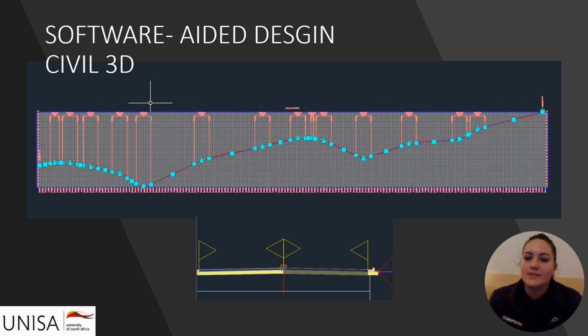The corridor is the physical road being designed. This will use the vertical curve from the profile and the assembly created to design the road. The minimum horizontal radius must also be stated, and all horizontal criteria must be included for the road to be deemed accurate. From here, the levels can be visually interpreted as being steep or flat.